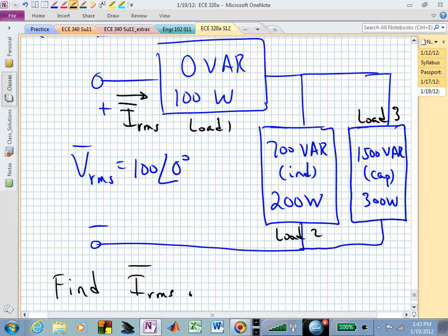Maybe if your power factor is 0.9, you have a tax of 4%, and if it's between 0.8 and 0.9, maybe it's 10%. It may not be a linear tax, because that's not necessarily a linear relationship, this power factor. Does everybody understand how you might approach this?